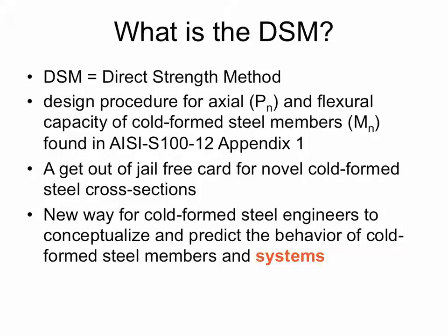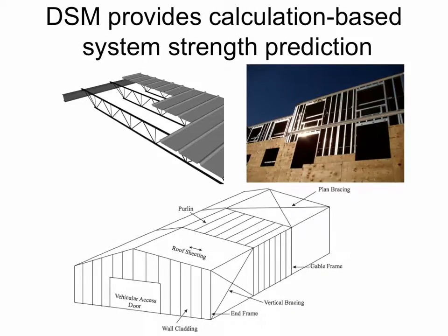As I mentioned, the big thing for me and for you today is to get you excited that you can actually calculate with equations and some software the behavior of a purlin or a girt in your wall or roof system. So you don't have to rely necessarily on the R factor method, or if you have, for instance, rigid insulation in between the panel, your through-fastened panel, and the purlin, then you can calculate the capacity of the girt or purlin. So it's pretty exciting.